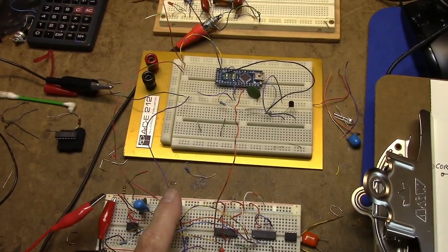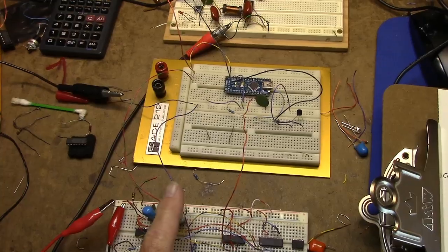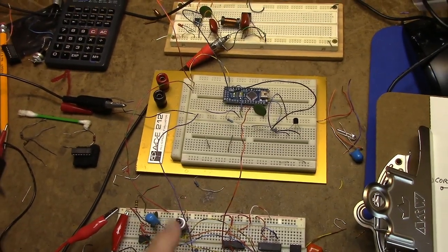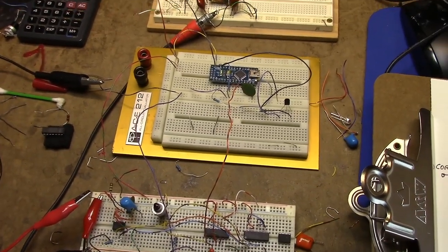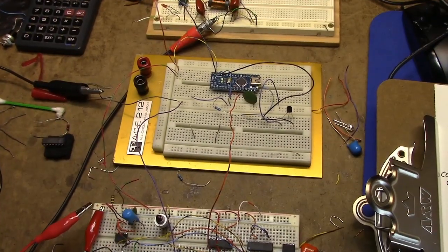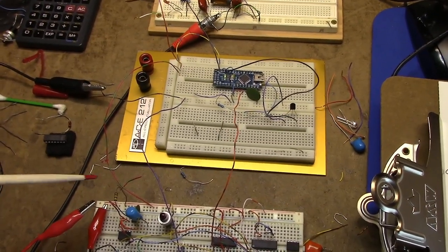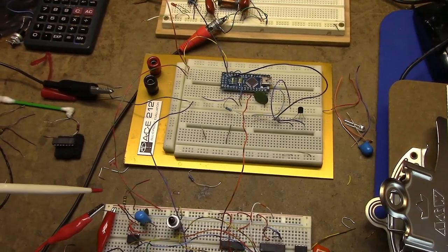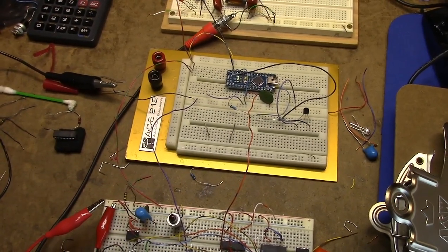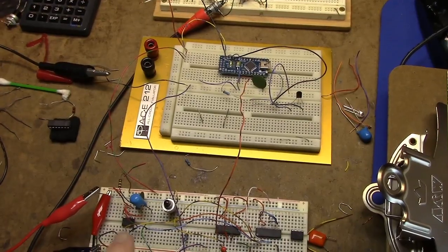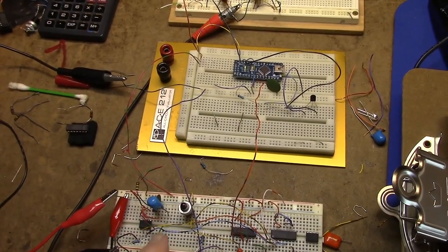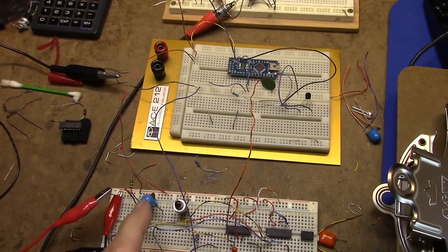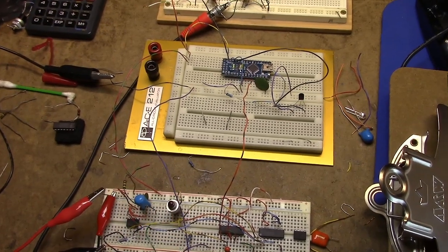And now I can push it again, nothing happens. And this would be for 10 minutes, or 9 or 10 minutes. And then at the end of that time, it can be triggered again. This resistor, of course, will be replaced with a 1 meg resistor, which will increase the time. So now, after the timeout of this monostable, which probably is about now, I should be able to trigger it again.